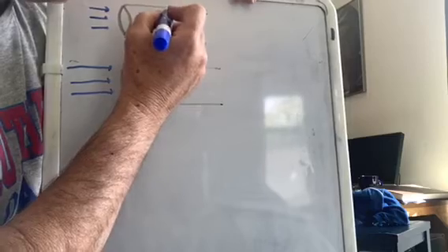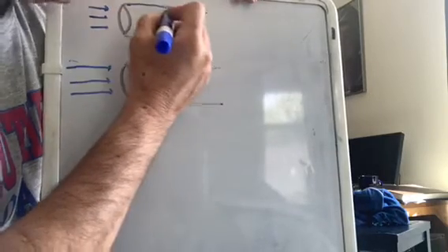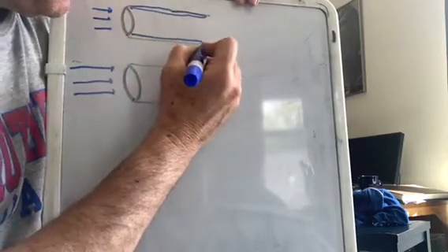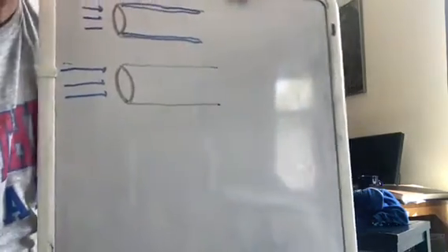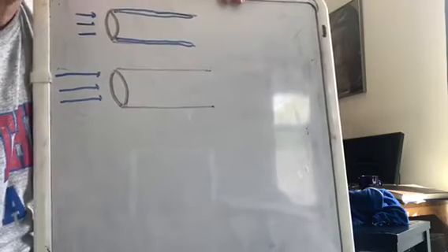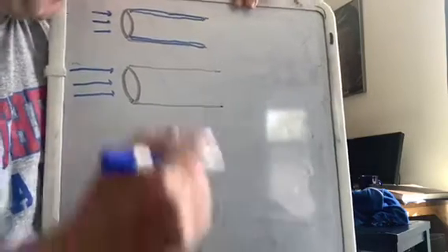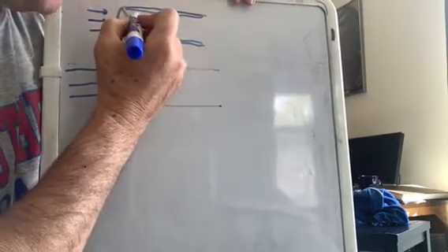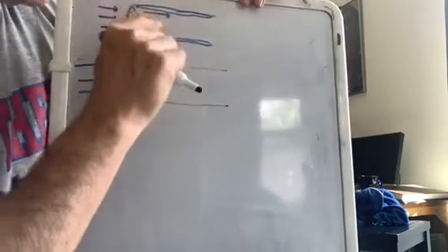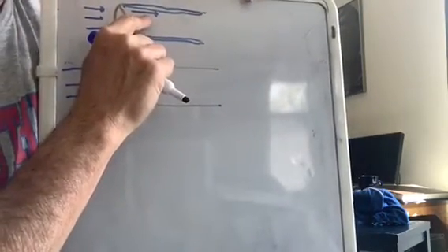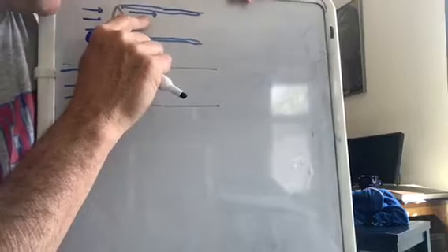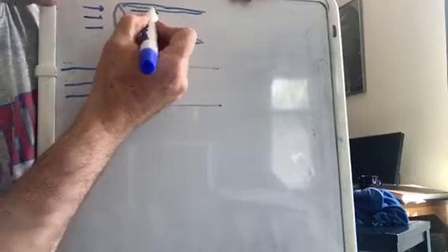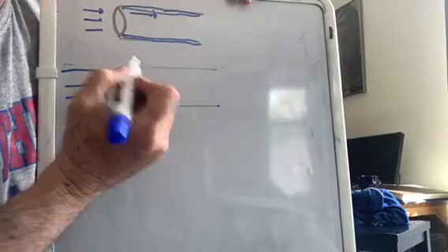Remember from your heat transfer, remember that we have this layer that hugs the wall that follows the no-slip condition, and that means that layer actually doesn't move. And so as a consequence, we have this layer of fluid entering, okay? And there is viscosity, which is an attractive, cohesive force, and it tends to slow this layer down a little bit and create shear.